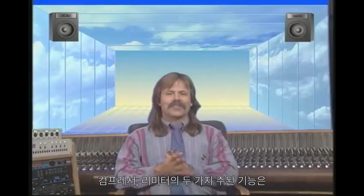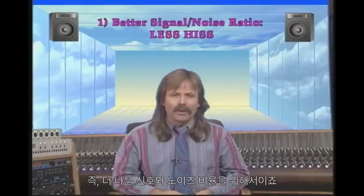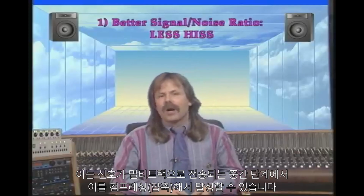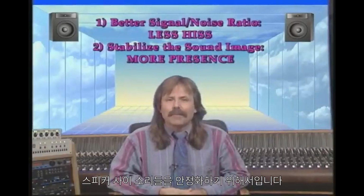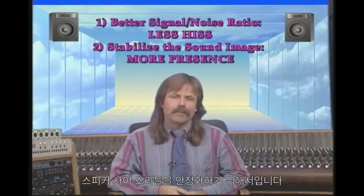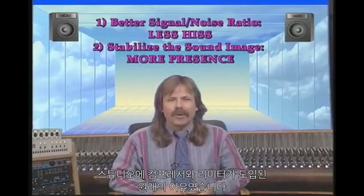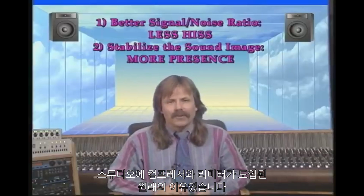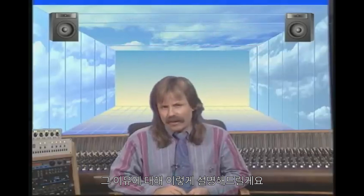The two main functions of a compressor limiter are: one, to get less noise on tape, a better signal-to-noise ratio. This is accomplished by compressing the signal on the way to the multitrack. And two, to stabilize the sound between the speakers. The first function, to get less hiss from tape, is the original reason that compressor limiters were first introduced into the studio. Let me explain it this way.